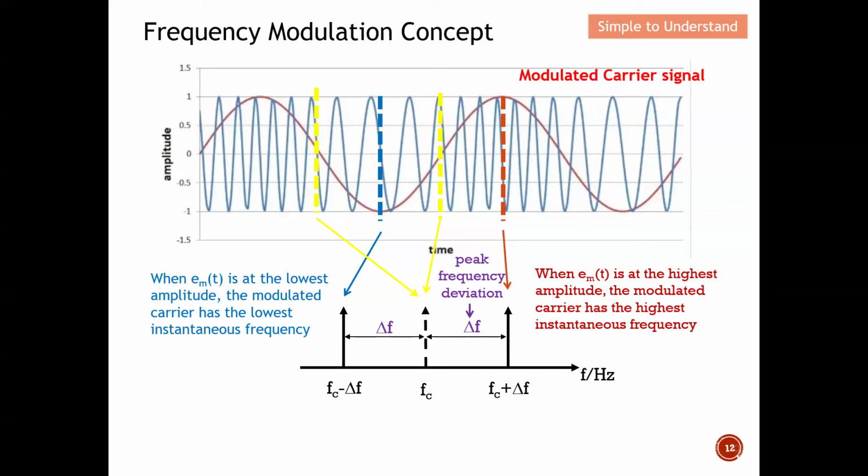And this is how we can represent the modulating signal. Over here, you can also clearly see that this signal used to be a low frequency, but once I put it into the carrier, the frequency can be increased. Remember, as I mentioned earlier on, the modulating signal has a lower frequency as compared to the carrier. Hence, because of this, I successfully moved the frequency from a lower frequency to a higher frequency. So basically this will give you the concept of frequency modulation.